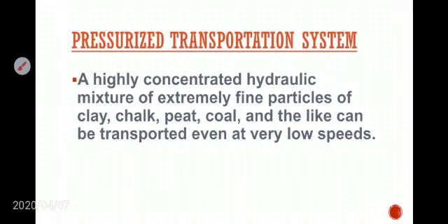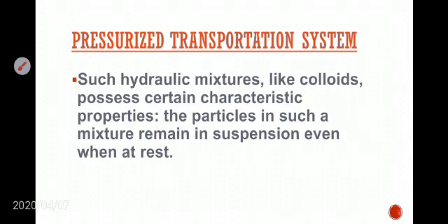That means their particle sizes are very small. So this clay or chalk or peat or coal, at high pressure incident onto their faces, can totally get crushed. After crushing, they will be mixed with the water in a thick, viscous form of slurry, and this slurry will be transported through the pipelines at the same speed without increasing or decreasing the pressure.